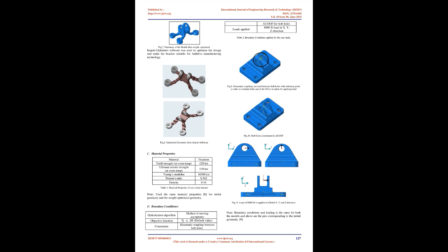Structural finite element analysis is performed on the original bracket to observe the stress distribution in the part. Fig. 12 shows the von Mises stress distribution for all the load cases. The areas shown in the blue color of the part replicate the inefficient use of material. This represents the negligible effect on the performance and still having the scope to optimize the geometry. Note: the final design satisfies yielding condition with safety factor from 1.1 to 2.26.